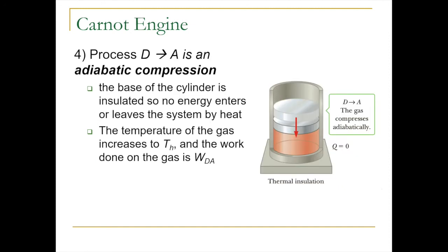And to finish the Carnot cycle, we do an adiabatic compression by replacing the cold reservoir with the thermal insulation yet again. And in that process, the gas will continue to compress, but it will do so adiabatically because there is no energy exchange with the outside environment. And the result will be, again, negative work being done by the piston, or positive work being done on the gas.